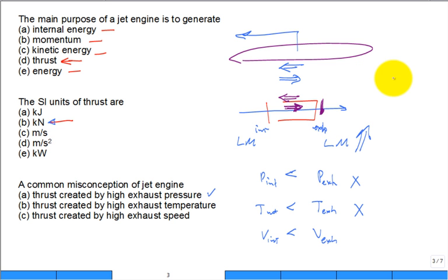If you put your hand there, it's a blockage. And the flow that would normally go straight through that area without the hand has to come to rest and then turn and go around. And there's probably a stagnation point right there. And so the pressure built up right there, didn't it? By putting your hand there.